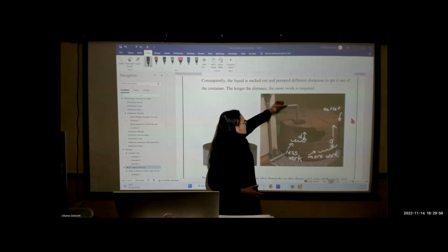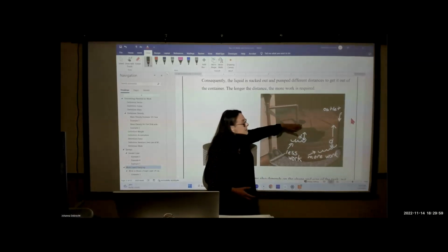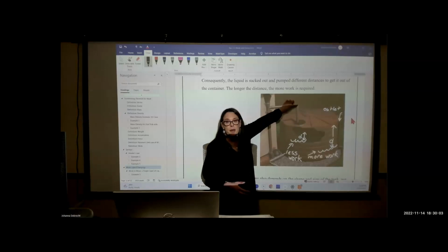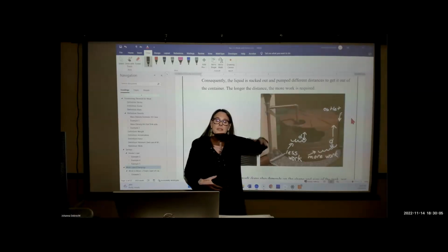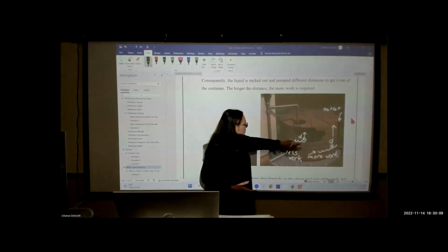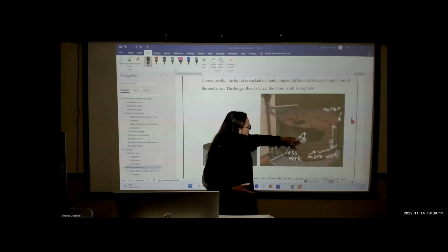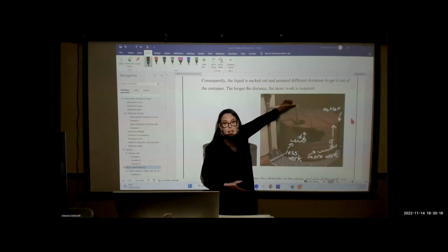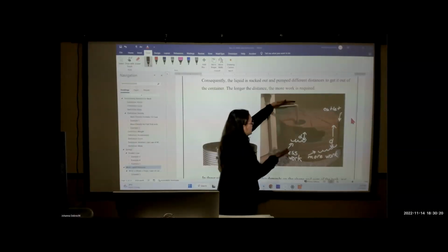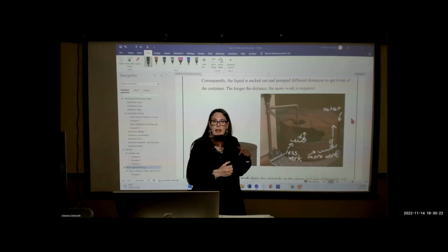Now, this pipe right here is the outlet pipe. And notice that it's not at the upper level of the tank. It actually extends above the tank. So that has to be taken into account when you're computing the work done. Now, if the water level was here, it would have to move to the top of the tank, then to the top of the outlet pipe. And the work required to do that has to take this full distance into account.